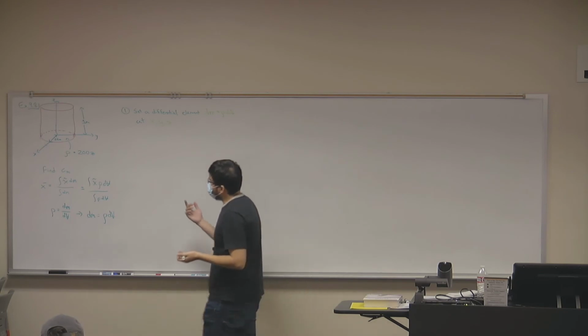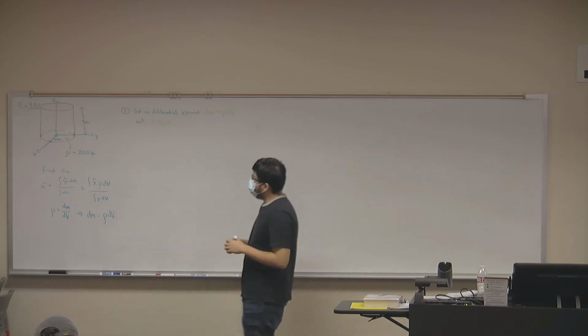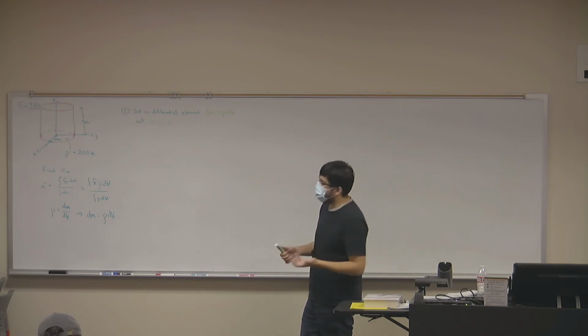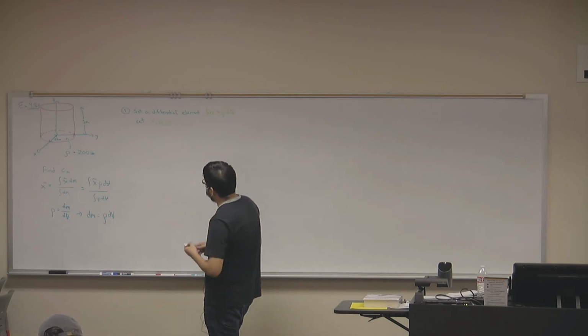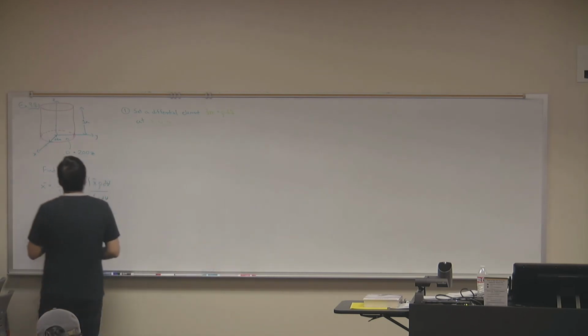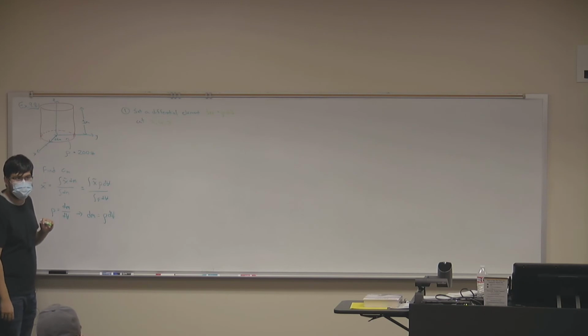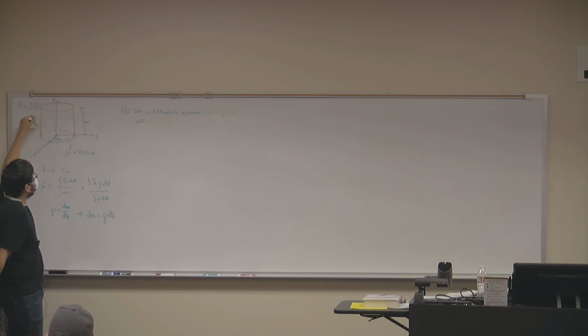You can choose a point wherever you want here. You'll see that it actually doesn't change anything, right? Your integral will still be the same regardless of where you choose your point because of how this problem is set up. So I'm going to set my differential element. What do you think is better for us? Should we set an element maybe in this direction where the cross section is a rectangle? What do you think we should do? No. So what else should we do instead? Circular. Yeah. Okay, so maybe an element cutting right through the xy plane, or in the xy plane direction, so that our element is actually a circular plate, right? So we're going to do that. We have our differential element.